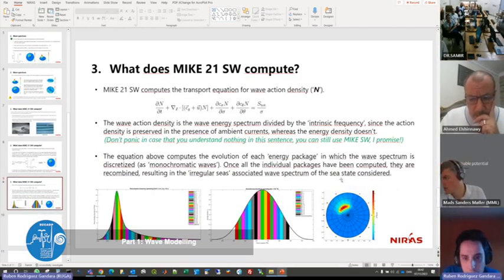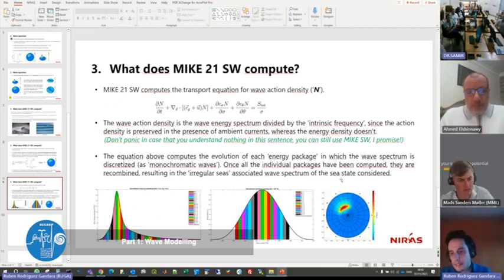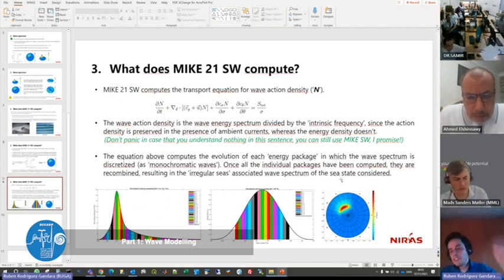And the last concept that I showed you about this was in the case that you don't have wave spectra, real 2D spectra at the boundary to impose how much energy makes it into your model. I was showing you what Mike does if you don't have that information. So if you are starting basically from, I just know for this time, the significant wave height, the peak period, and the mean wave direction. So based on that information, what I was telling you is that this is what Mike is going to do.